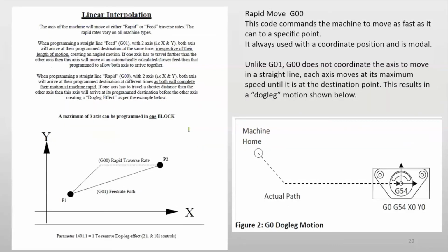Whenever you use a G1 line move, it takes the shortest route, because it wants to go from point P to P2, but it's not the fastest one. If I want the fastest move, I use the G00. Rapid move puts the machine at its fastest possibility. All these actuators work together, putting much more pressure on the machine. Because both gears work together and it doesn't want to lock, it puts it at 45 degrees and makes it a two-part move, not one move. So it goes like that and goes like this. You can see it's a G0 rapid.